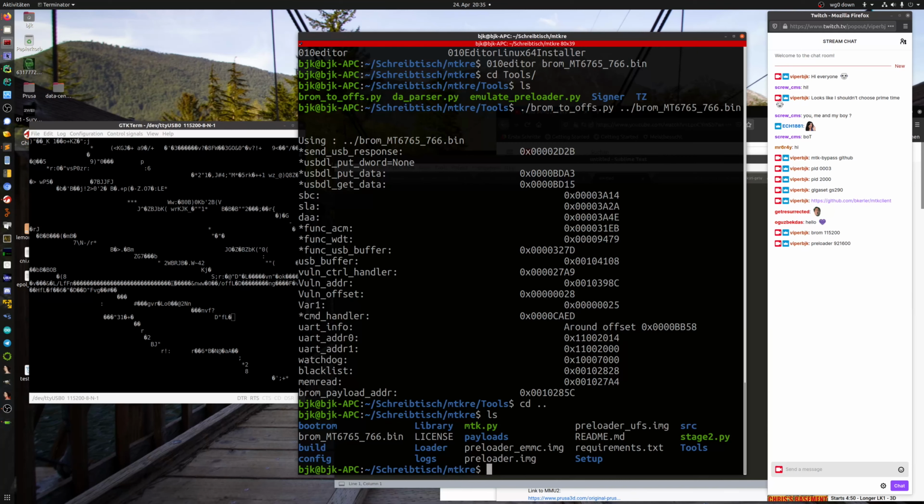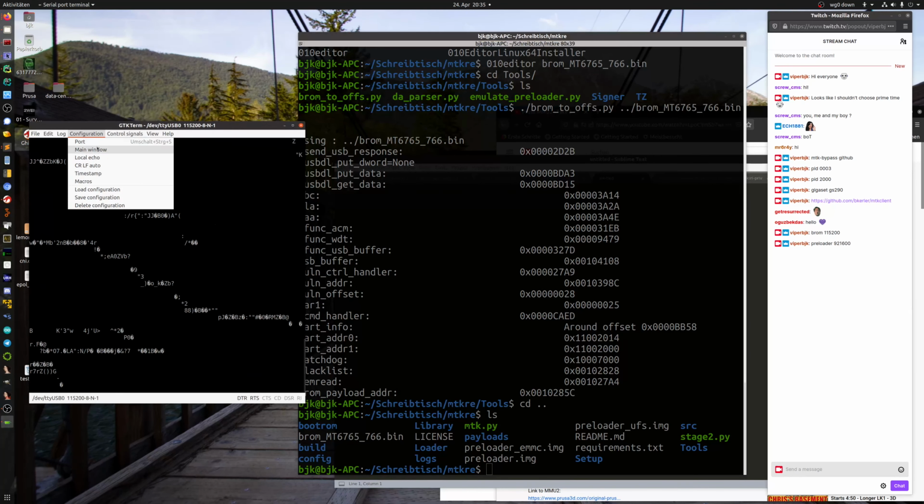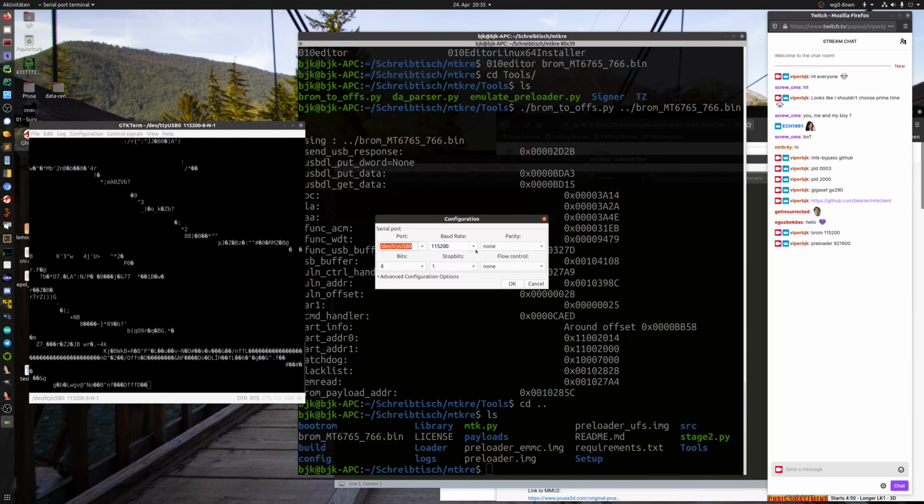So there are two ways to do that. The first one is go and grab a firmware where the preloader is included, and the second one is to dump it. Dumping isn't that simple, because you can't read without the preloader, because the DRAM config is missing.